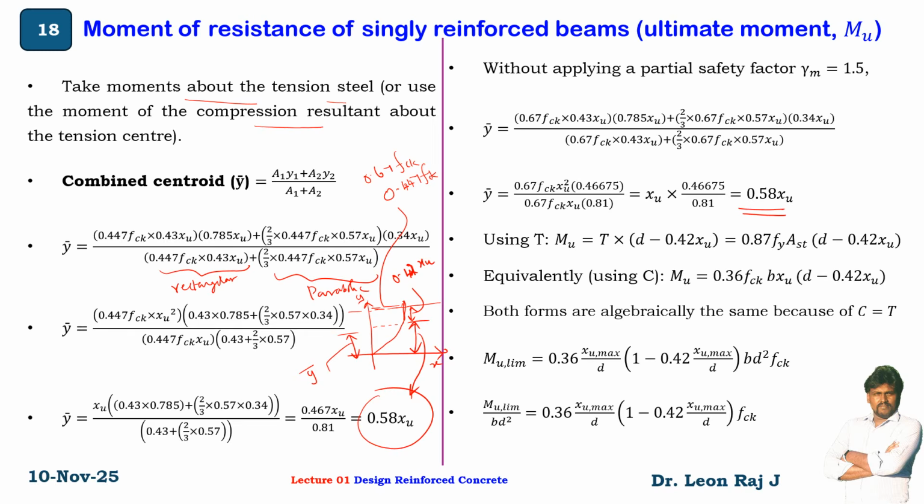Here y bar equals A1 y1 plus A2 y2 divided by A1 plus A2, and you will get the same value.